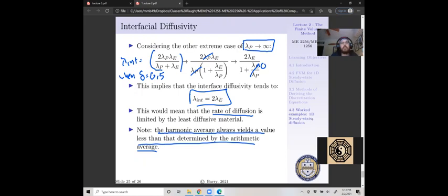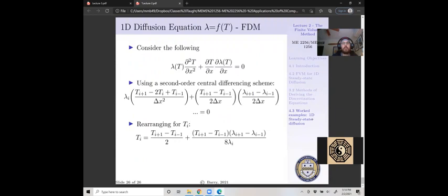And what we're going to recognize is within our harmonic averaging, we're going to have an underprediction of that diffusivity. Is it going to be much? Well, in that previous example, using a harmonic average we got a value of 7.5, whereas if we did the arithmetic, we had a value of 8. That's about a 6% difference within our system. So slightly less diffusivity and slightly less underprediction. So those are two really important things to consider.